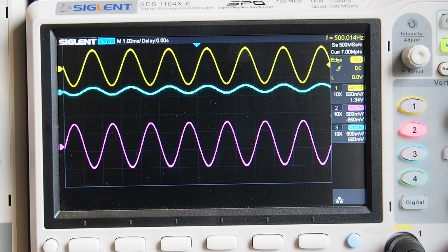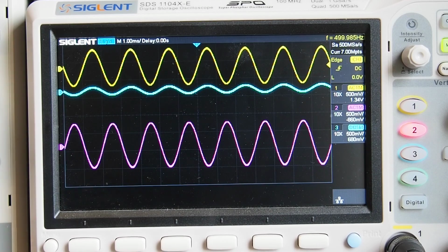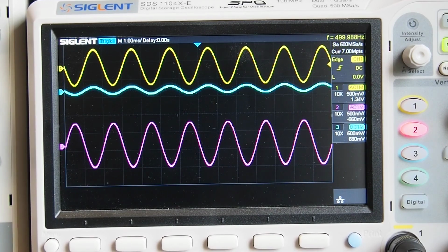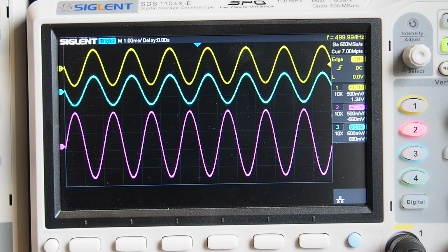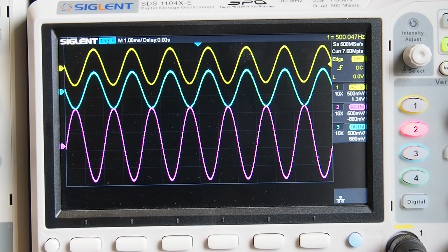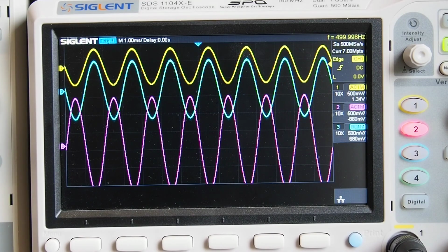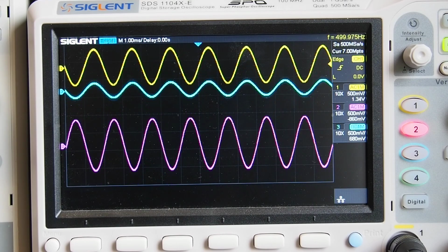So here's 100 millivolts, and hopefully you could see a change in the size of the trace there. That's off, on, and if I now step that input up through 100 millivolt steps, so 200, 300, 400, 500, you can see the op amp is indeed adding up the two signals. And if I continue, okay, it's going off the scale, but I'm now at 900 millivolts on channel 2 and it's adding it up.